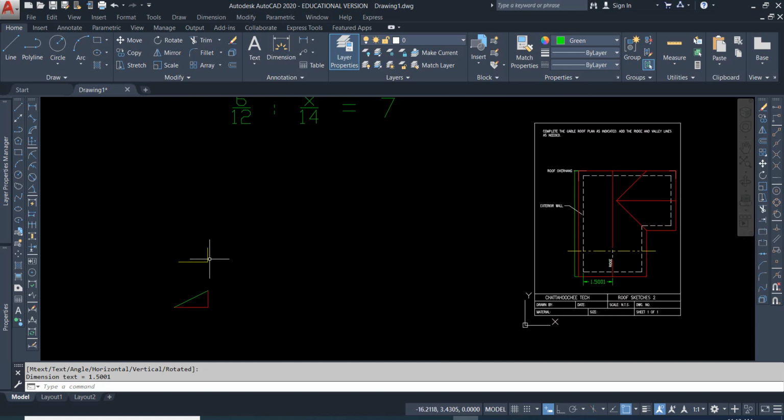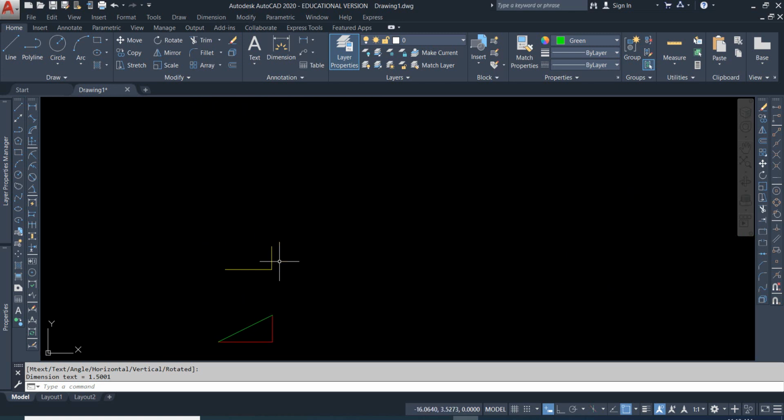All I need to know is the height right here. And this one, I've already done it and drawn it. And so if I close that in and then mirror that, that gives me the pattern that I would cut out for my gable end.